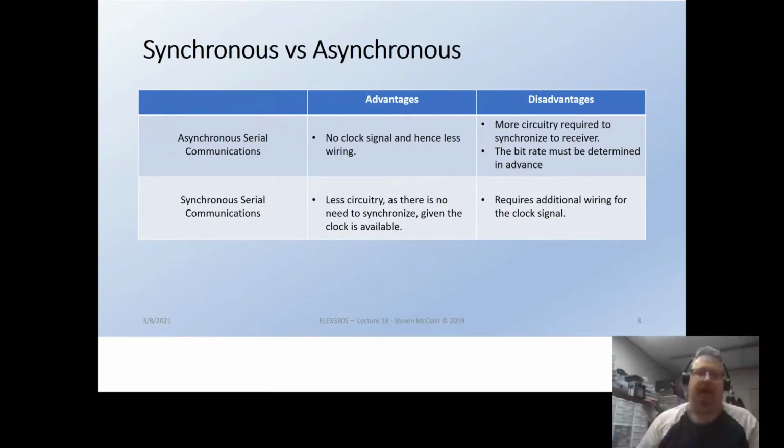So you could run it at any speed, as long as the parasitics of the physical connection were acceptable enough that you could actually see the change by the time the clock edge happened, and you were able to pull the clean edges out of the noise. You could run it as fast as you want, right? In a synchronous system. But in an asynchronous one, the faster the clock rates are, the harder it is to actually keep them in sync.